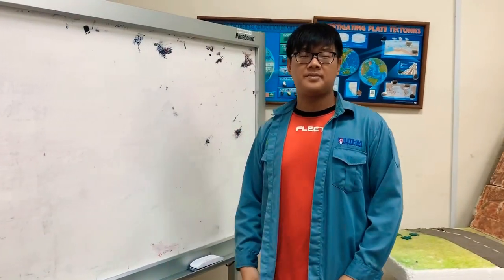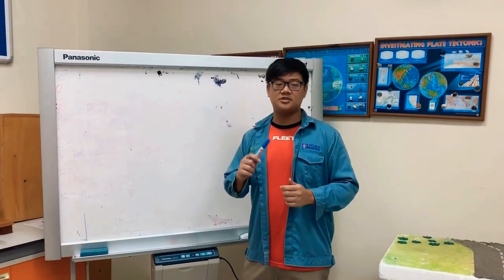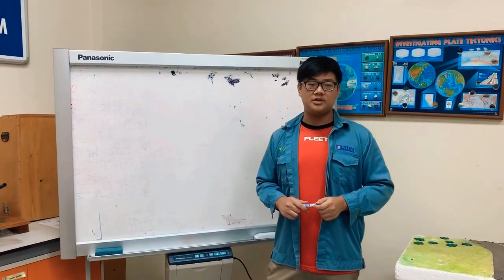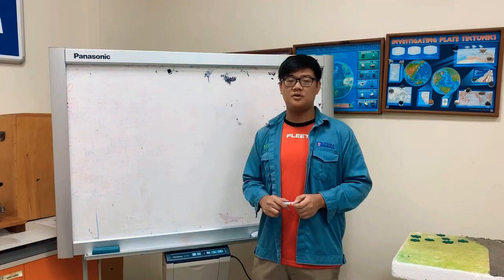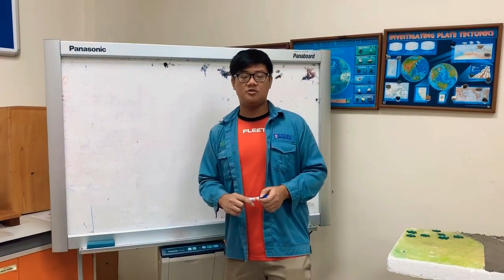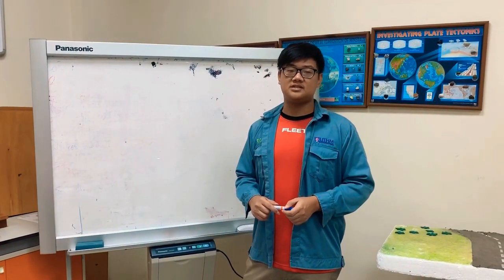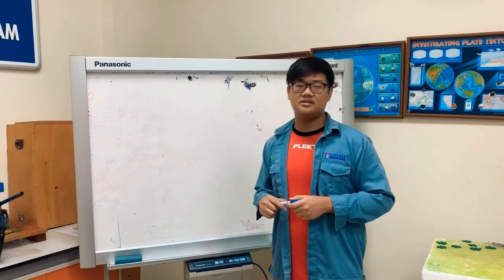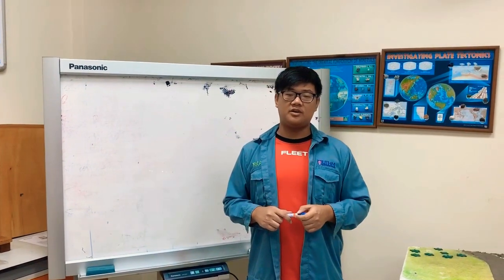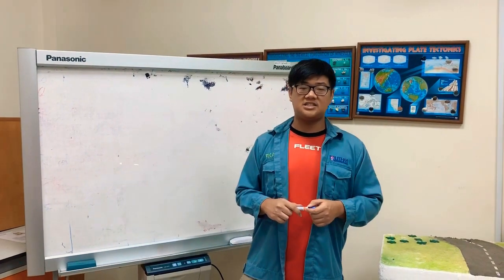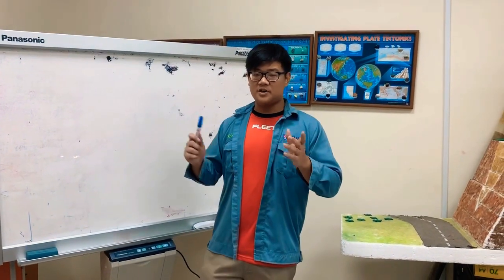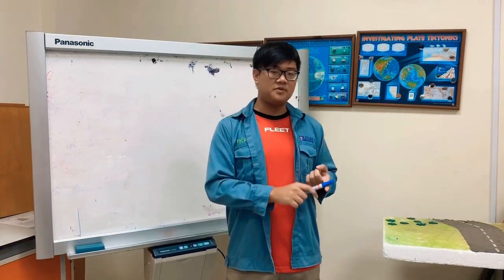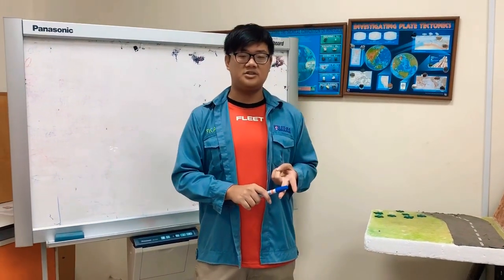In conclusion, in Malaysia, the soil normally found at coastal areas is marine clay, which is the title of this case study, and it is the most problematic soil with very poor soil properties. To do the stabilization, among all the methods that we have already stated before, rice husk ash, also known as RHA, is the most suitable method to be used. It is because RHA is very cheap and very easy to find in Malaysia.